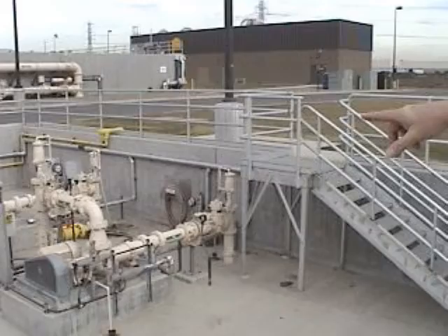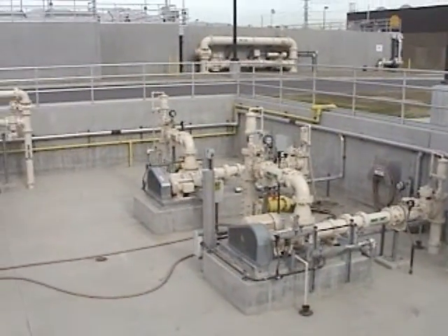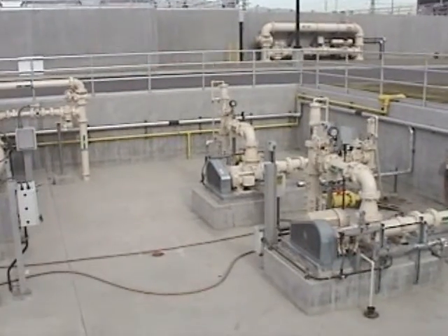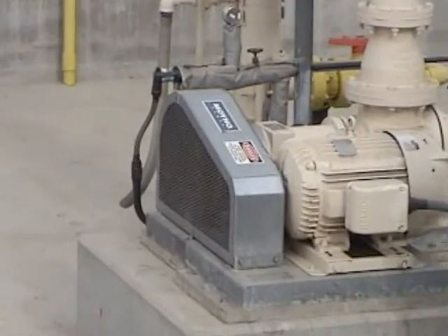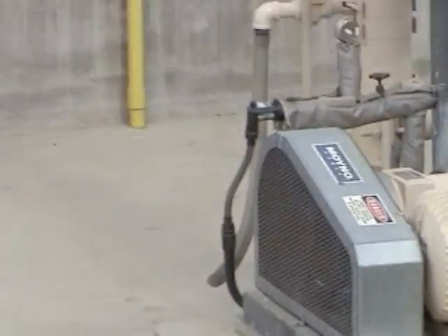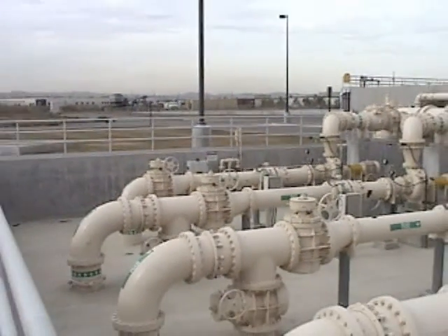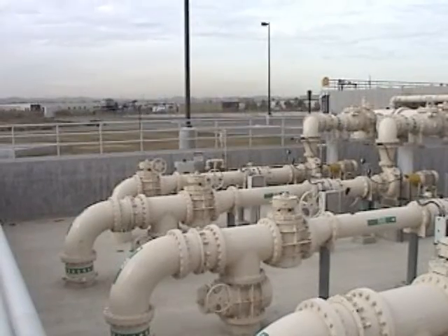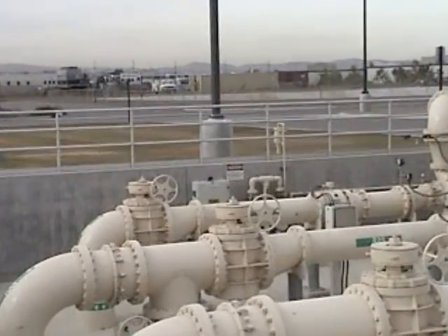Typically, we're only going to run 1 WAS pump, and you can see it over there turning very, very slowly right now. This structure here has sump pumps in it. It has alarms over there in the corner, which, if you had a flooding condition here, will send a priority 1 alarm. A klaxon will go off, and that beacon on top of it will light.